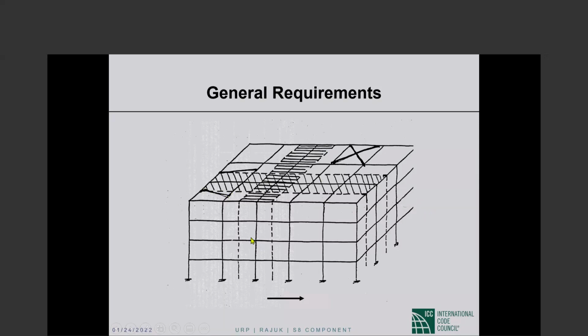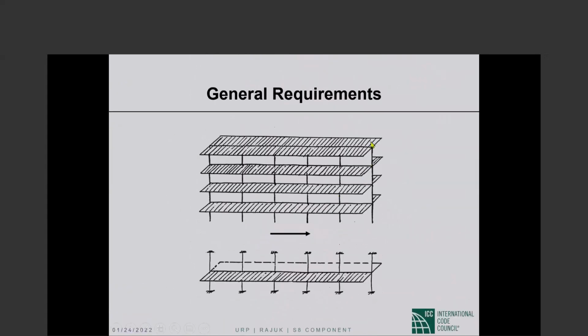Now, when you take a chunk like that out of your building, this is what you end up with: a set of columns supporting the strips of slab, and the strips of slab run between panel center lines. Okay. Now, when we are considering lateral loads due to wind or earthquakes, this is our subsystem below which we cannot go.